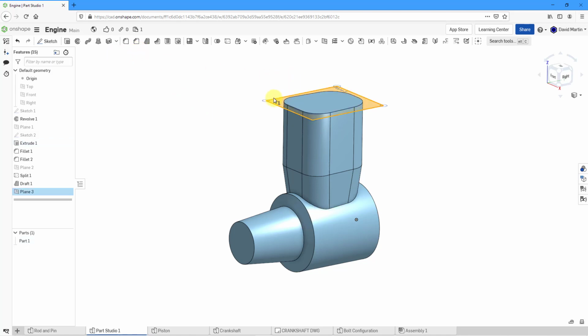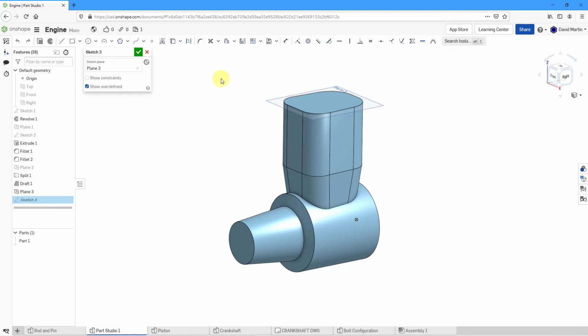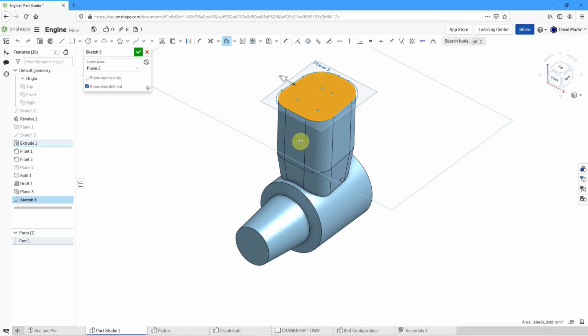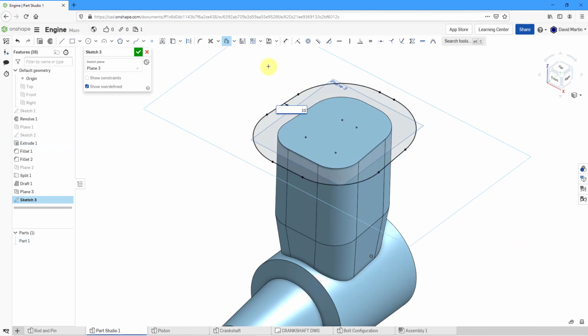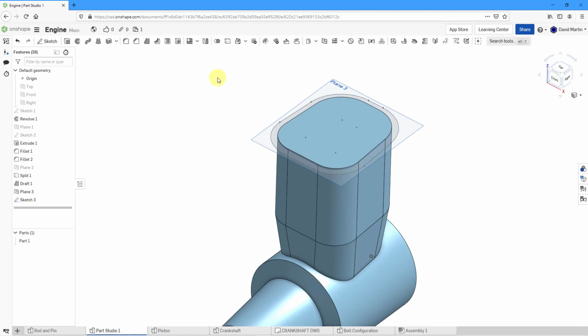Let's select our plane and create a sketch. And for this one, I am going to offset from the different surfaces or the faces of the surfaces. So that's going to be from this command, and I will offset this face. Right now it's showing inward. Let's offset to the outside. Let me drag this a big distance just so I can see the dimension that I want. And right now it's giving me a value of 35. Actually, I want this to be a value of 10. And I can hit the check mark.